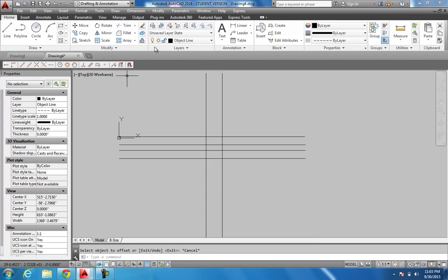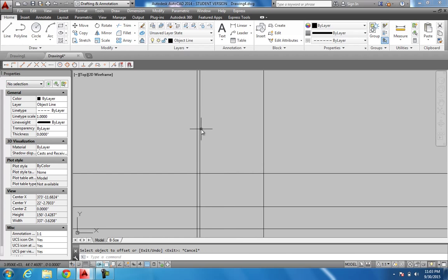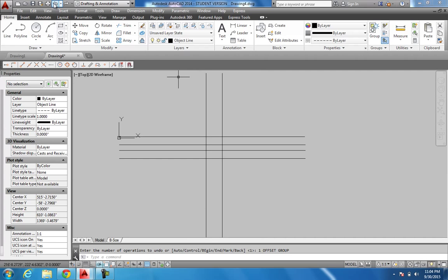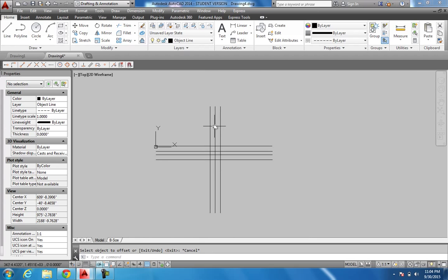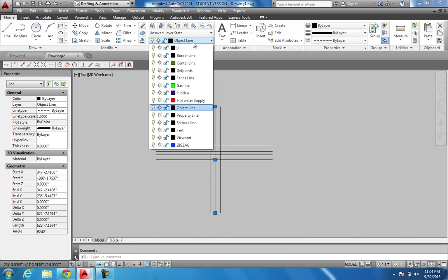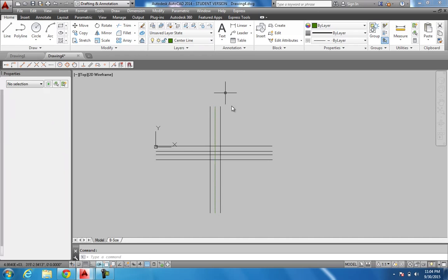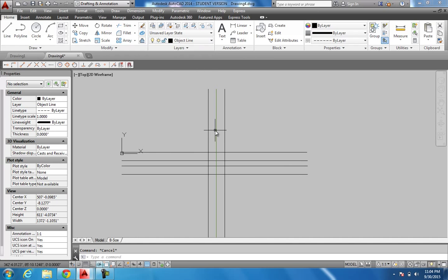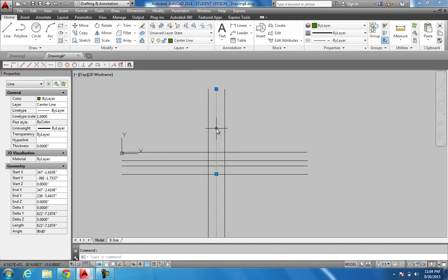These also have center lines in them, so I want to offset. Half of 60 is 30. And you see what I did? I did 30, and I didn't put any feet on it, so I did 30 inches. So I have to go back, hit my offset 30 foot, put that in there, and what I do for that center line is click on it, come up here, and change it to center. So much easier is that you change it as you go.